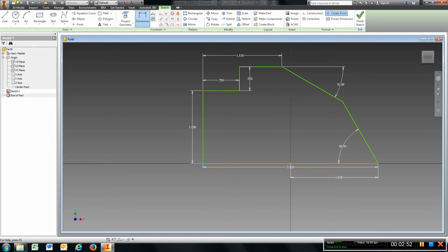I can go ahead and put that hole in the center here, so I'm just going to drop that in. It is a 0.75 hole, and it is located 1.5 inches from this line to the center, 1.5, and from the bottom up it is 1 inch, 1, enter.